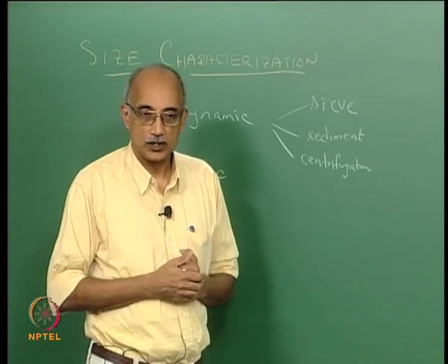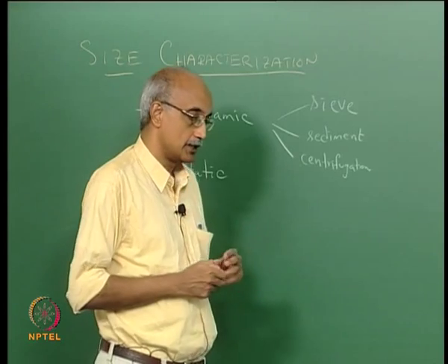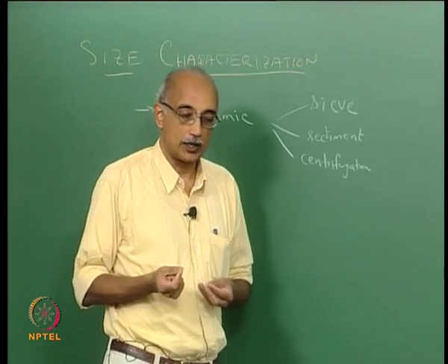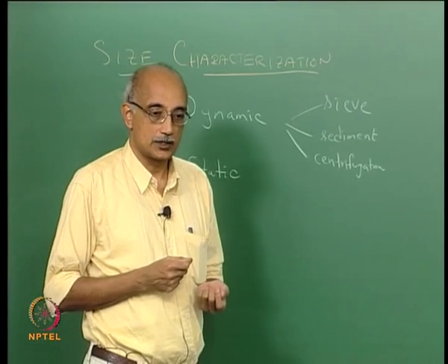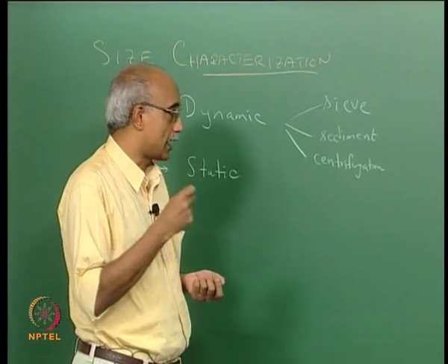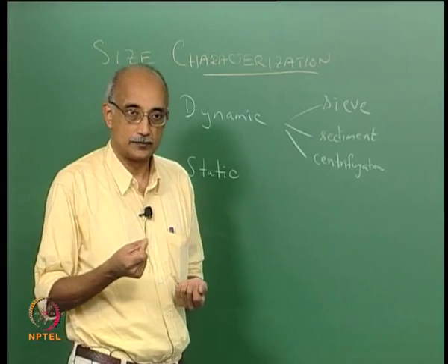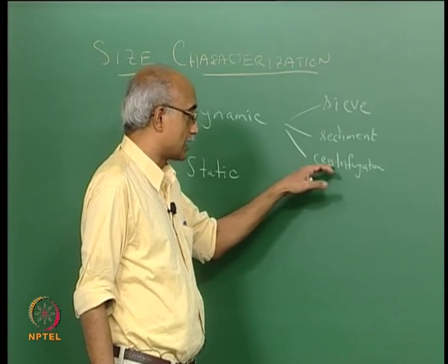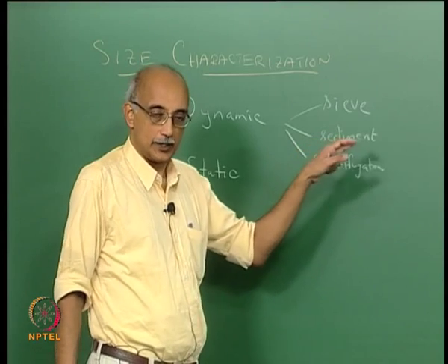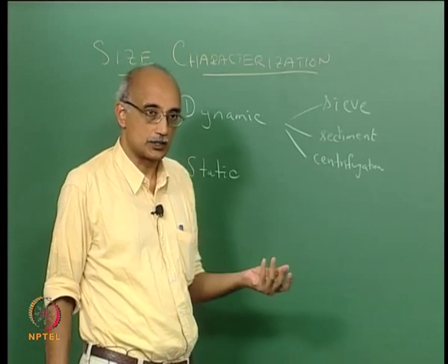So, you achieve separation by size, and then you can essentially capture the samples and do sieve analysis to characterize their size. Now, in this case, the characteristic of a particle that you are using to do your dynamic size analysis is its action under a centrifugal field, which is a supplement to the gravitational field that you experience in sedimentation.